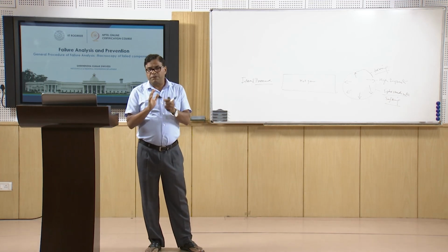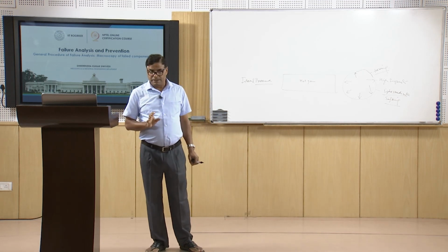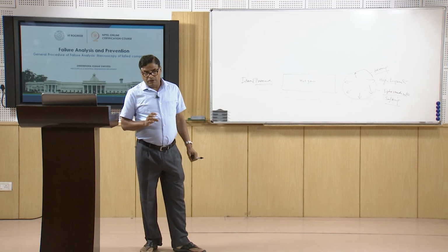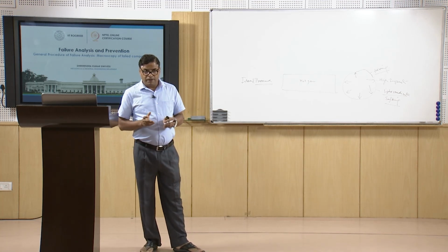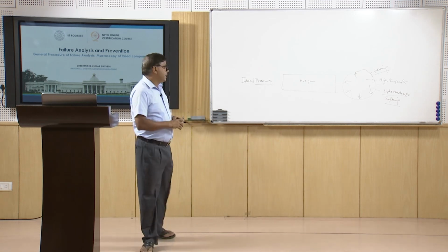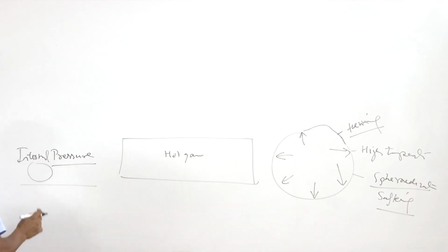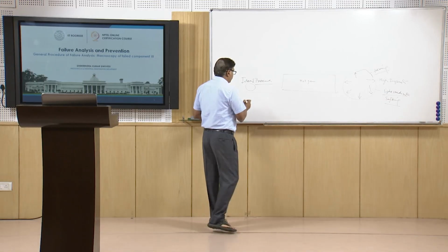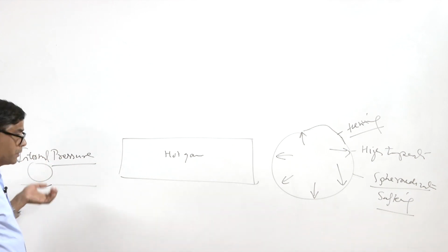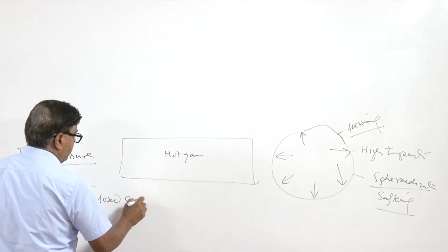Some of the cracks which are very tight and very close may be difficult to detect under NDT. If such cracks are present, they indicate the possibility of development under cyclic loading, or that the component has been subjected to shot peening, or to inappropriate heat treatment like quenching. In the case of shot peening, the shots are directed onto the surface continuously, and the material is not able to absorb those shocks and deform enough, so it forms cracks, and the continuous application of shocks leads to the closing of these cracks also. So, these will be very tight and closed cracks.